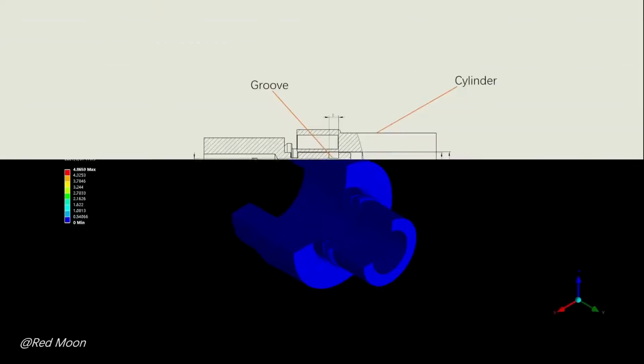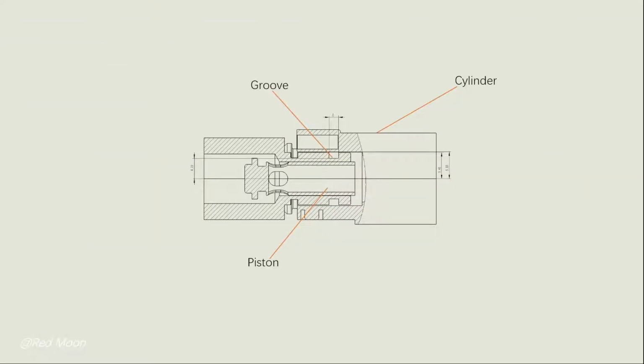Okay, let's get started. Before we jump into the simulation, let's take a look at the model I used. This model is a joint with a male end and a female end. The O-ring is placed in the groove. The groove is a narrow cut on the piston. In this case, we will call the radial seal a static piston seal. Under the operating condition, working fluid will go through the joint. What we're going to do is test whether the O-ring here can prevent the penetration or not.